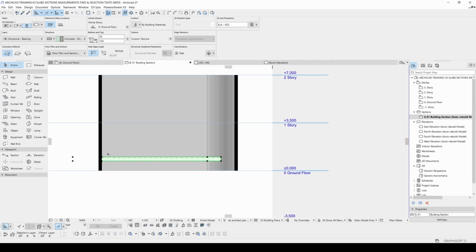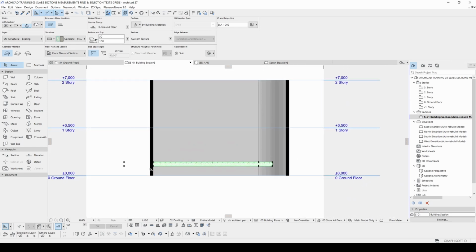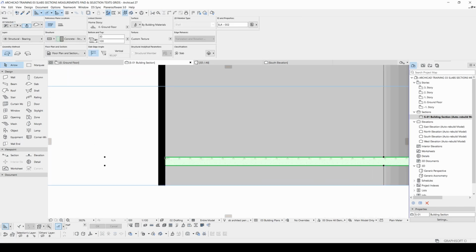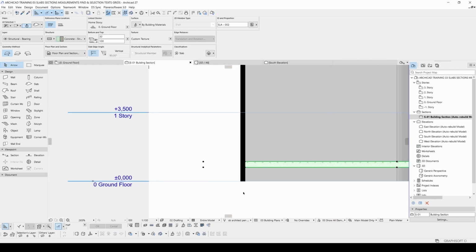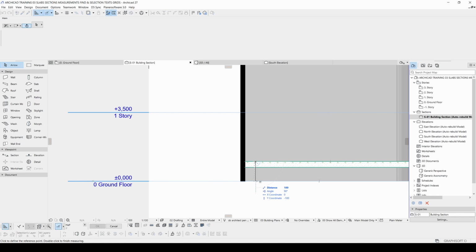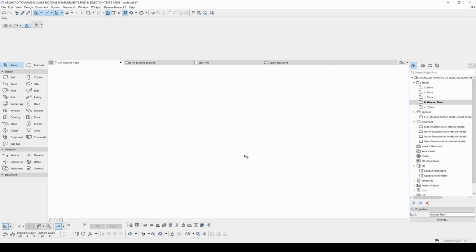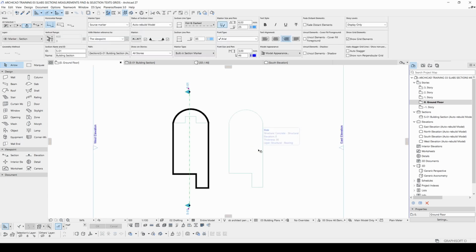You can select and modify your elements such as walls and slabs. You can change the heights. And this top position is 1 meter above this ground floor. If you hit the M, you will see it will say 1 meter or 100 centimeters. If you hit F2, you will immediately go back to the ground floor and you can continue your documentation progress, such as this section. As you can see the horizontal range. Now it's infinite depth. If I move this section, I will see everything.